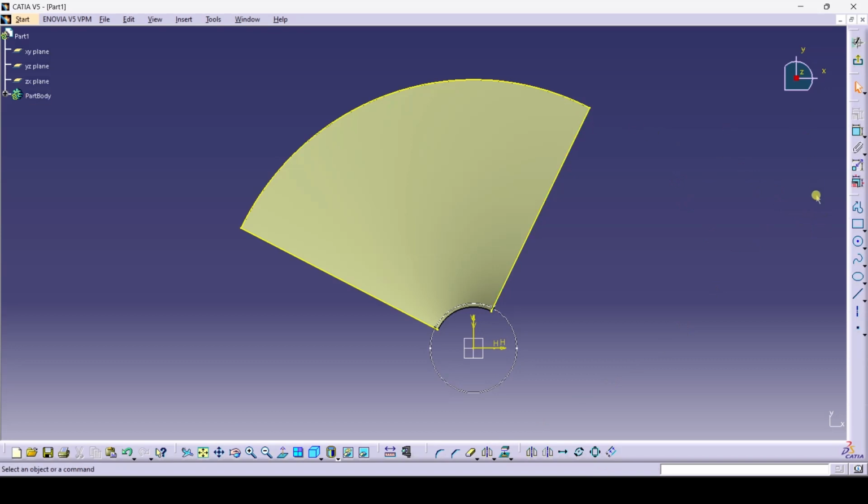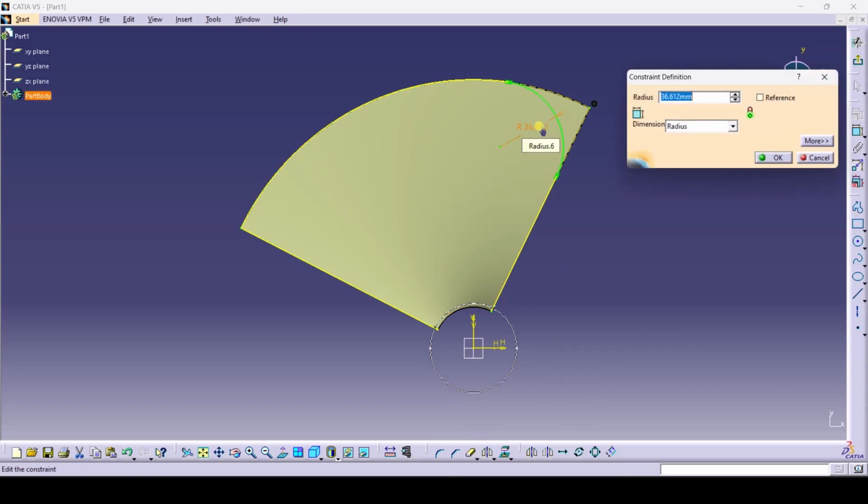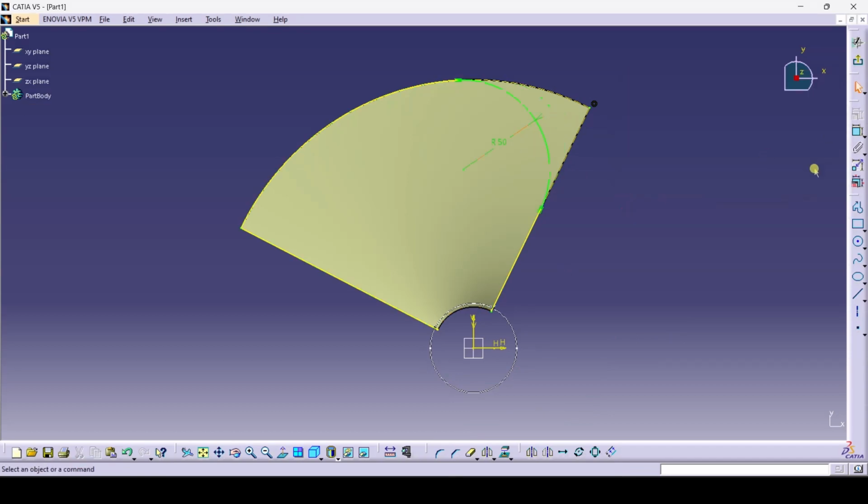Then we can convert the sharp edges into a curved one. So here I have taken 50. First I will show a blade with both sides 50 mm curvature, because many blades will be like this. It will be like a symmetrical profile about this axis.